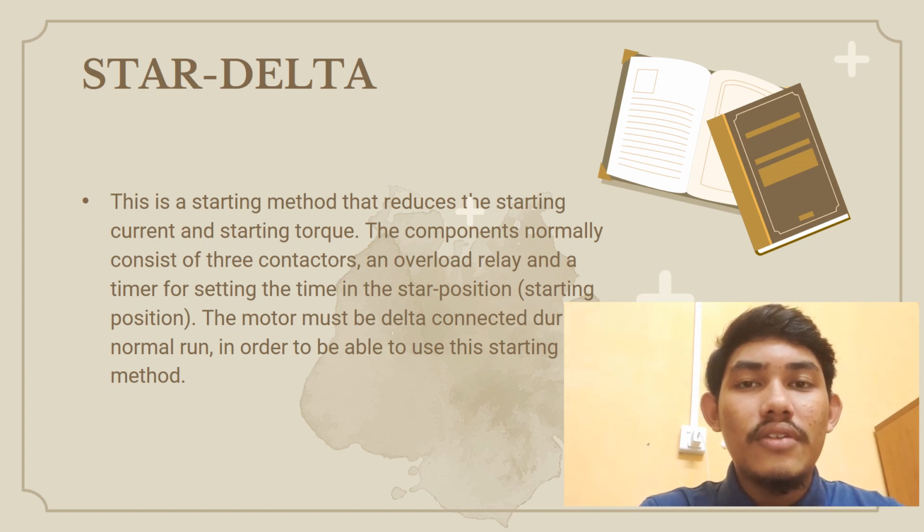When reaching approximately 80 to 85% of the motor rated speed, the load torque is equal to the motor torque and the acceleration ceases. To reach the rated speed, a switch over to delta position is necessary, and this will very often result in high transmission and current peaks. In some cases, the current peaks can reach a value that is even bigger than for a DOL start.